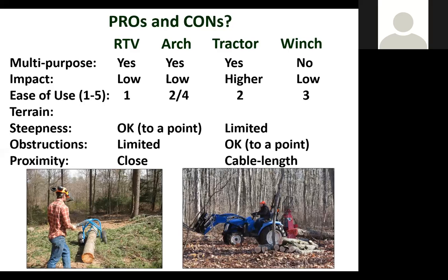The tractor, this particular tractor we have, because it is narrow, it's a little top heavy. We're very wary about operating it on a slope, either straight up and down or not at all. And even going downhill with a four-wheel drive tractor that's not articulated can be a thing you want to give some thought to. So it does have limitations in that way.